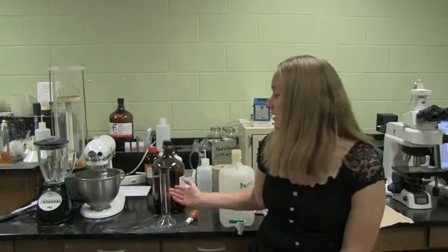One of the most relevant physical properties that define substances that are candidate shrinkage reducers is surface tension reduction in dilute aqueous solutions. This surface tension reduction will be our property in our quantitative structure-property relationship. Our training set includes 14 compounds for which surface tension of their dilute solutions were known or could easily be measured. Measurements were made using a simple tensiometer. These measurements help train our quantitative structure-property relationship model that will eventually be used to score the inverse design solutions.